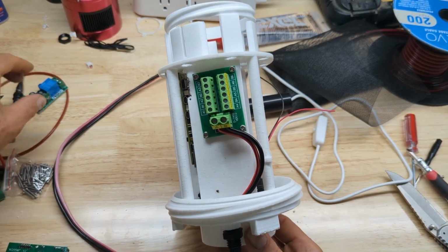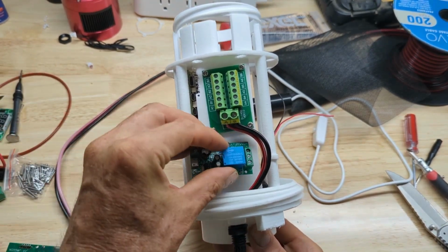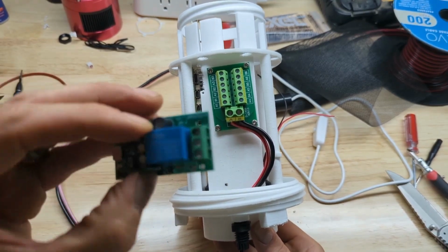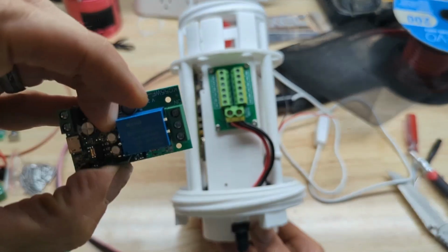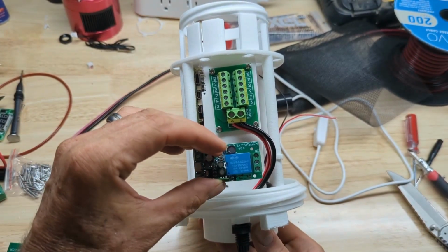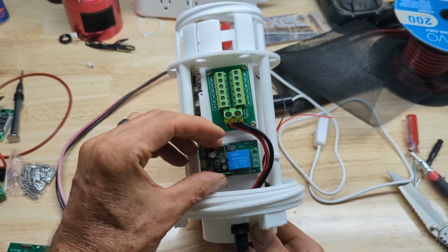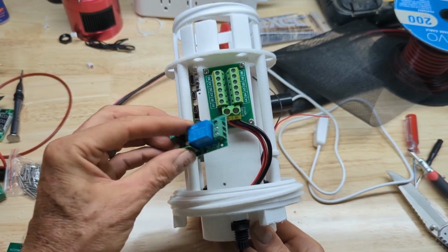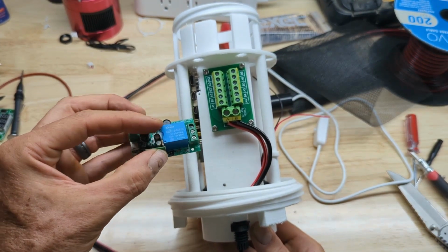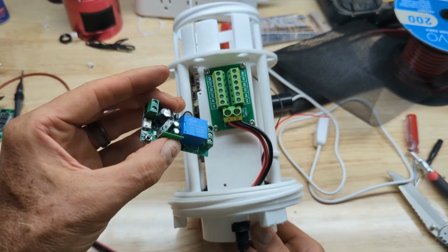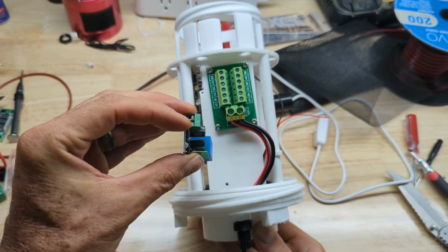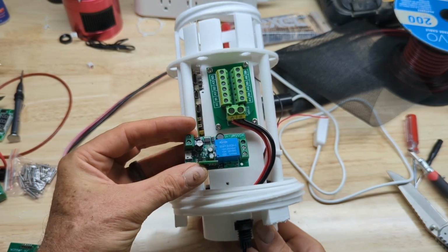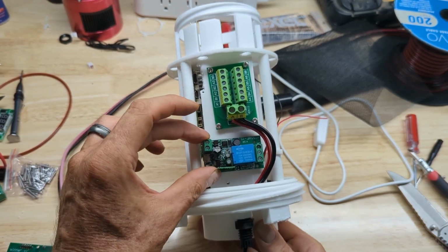So now we're going to start installing these power Wi-Fi modules. I'm thinking this small one would go very well right here. There's actually two holes. You can see there's two holes right here, and that's the only contact or connections they have. So I'll probably put a double-sided tape pad on there just to hold it in place, and then we'll get those screws threaded in there, because the main parts you need to access are this back side. That's where one device would power into, and then of course this device, this is where it gets its main power from to control the relay, the Wi-Fi, and all the other components that are on the board. So our next process will be attaching that.